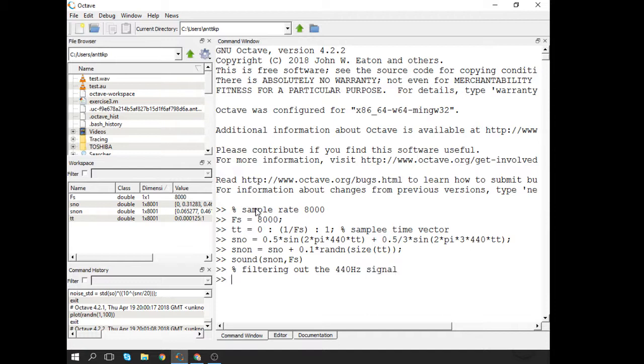It starts by defining my notch angular frequency, so that omega n is 2 times pi times the notch frequency divided by fs. So this is the complex angular frequency of the sampled signal. Next, we will put a pair of zeros on that angle.